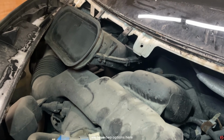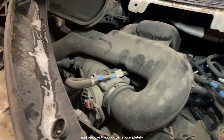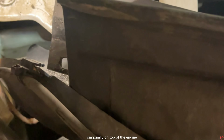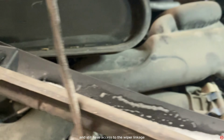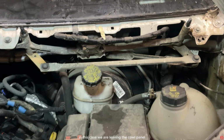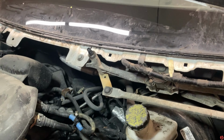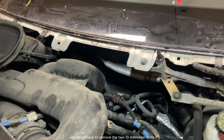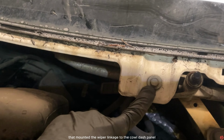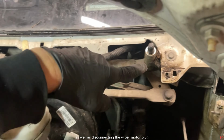We have two options here. We can either disconnect the windshield washer hose and remove the cowl panel completely, or we can simply sit the cowl panel diagonally on top of the engine and still have access to the wiper linkage and work with it. In this case, we are leaving the cowl panel diagonally on top of the engine. Before removing the wiper linkage, we would have to remove the two 10mm bolts that mounted the wiper linkage to the cowl dash panel, as well as disconnecting the wiper motor plug.